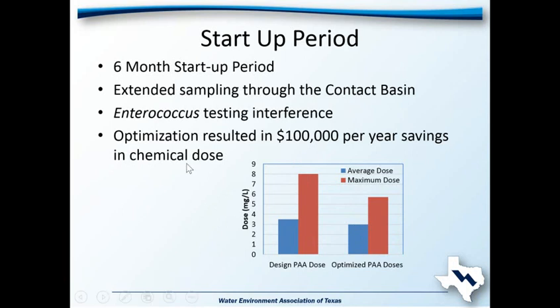One other thing we'll note is that with this 3.5 parts, our typical effluent is less than 1, typically more like half a part at the end of the tank, and that's at 20 minutes. So we do see a much more rapid PAA decay than what some of the other papers or panels have presented today. So there's certainly some variability here.